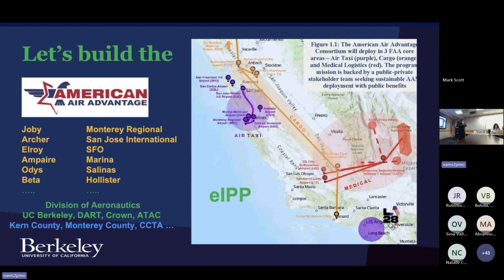The big problem is the approach to LAX. We look at the Part 77 surfaces, we stay below it, we have clearance, we look at the helicopter routes, we follow those, and it turns out we placed our vertiport on top of the transit center in LAX, the roof of the transit center. That's why we did it. Downtown LA, we actually did look at buildings and roofs and the convention center and the sports arena and the parking structure, and we picked something. We considered energy. If you're higher up, it's good in some ways because you're flowing down to LAX. So we looked at all of this. There we were careful.